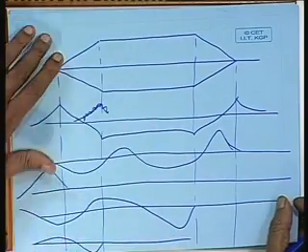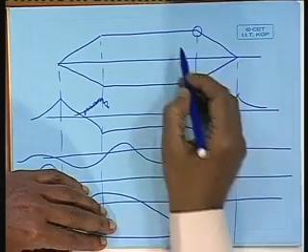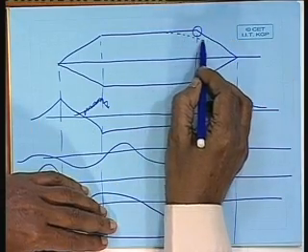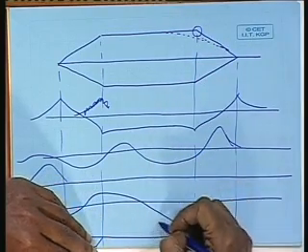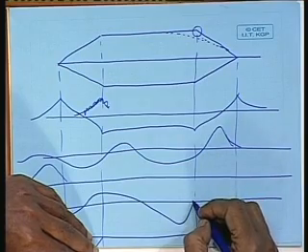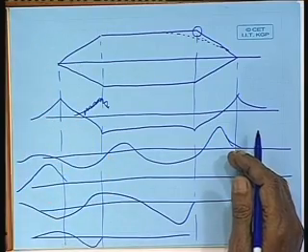Now, in the case of a wedge like this, these shoulder waves are very prominent, and you can see it because the shoulder is very well defined. In case of a ship, once we make it smooth, these waves are not so easily definable. Though a trough is visible, it is not so well defined. There will be a depression here and an elevation later on. Do you understand? So, what do you see when you look at the side of a ship? What do you actually see?